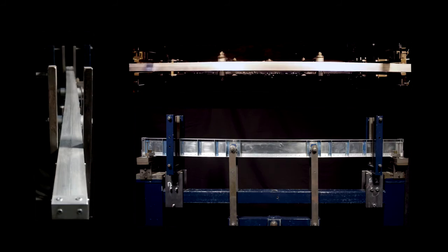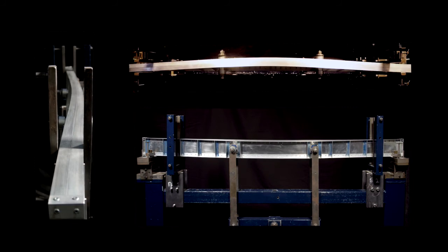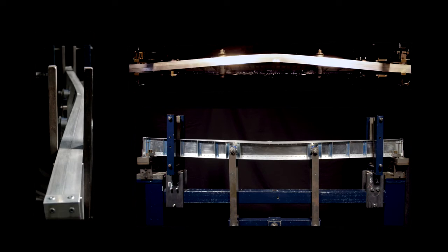Now, as the beam is loaded, the top half of the cross-section, which is in compression, starts to buckle sideways. However, movement is restricted by the bottom half of the cross-section, which in fact is in tension. The overall effect is to cause the middle of the beam to twist over as well as move sideways. The beam eventually fails by local buckling in the flange, which is induced by the lateral torsional buckling deformation.